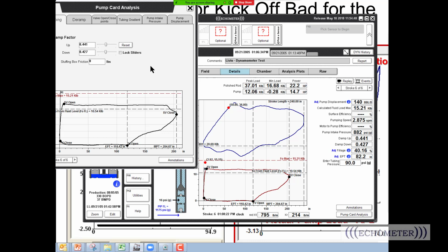And so we have information on our webpage about that, and that's another option you might try: don't set the pump below the kickoff point if you're experiencing high failure rates, or use some kind of friction device that reduces friction, like polyliner, or maybe co-rod with rod guides or slick rod guides. But anyway, once we draw the well down, it can be costly to operate if you have to stick your pump out in the horizontal.